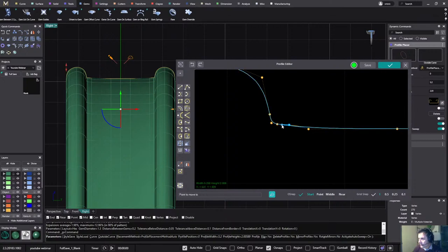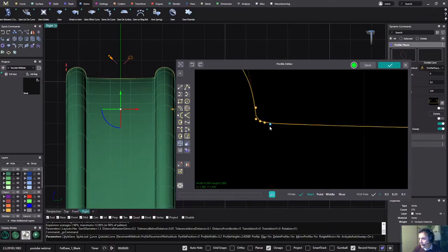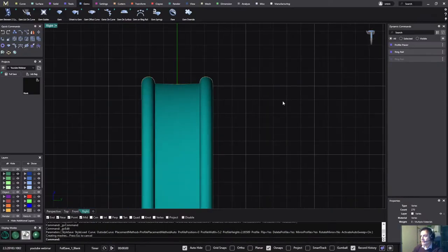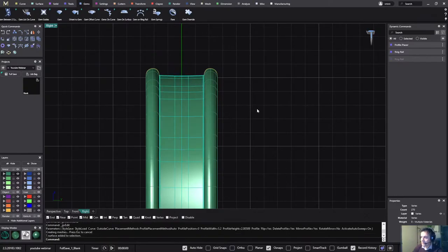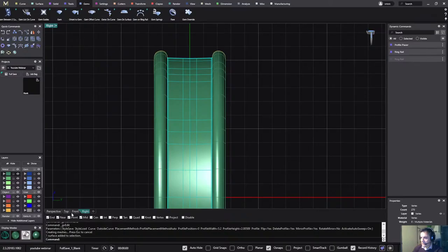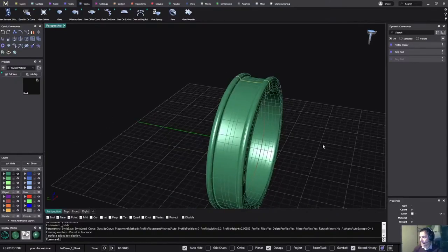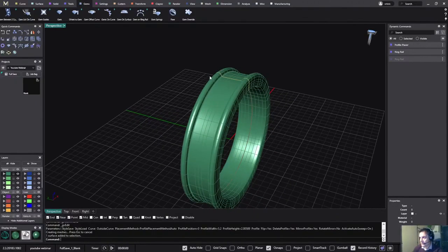All right, so now I can select where I want the surface to stop, because now this will be all the surface where I will be placing the stones. Okay, we keep it like this. Again, I validate, enter, and look now. If I select this surface, look what I get. I don't get this part, I don't get this part, I just get the central part, okay? So this is something that it's good to keep in mind, because then you can be more precise on where to place the stones.